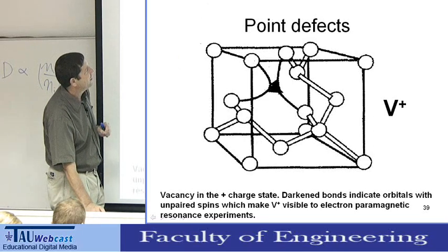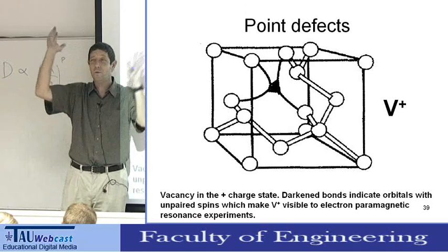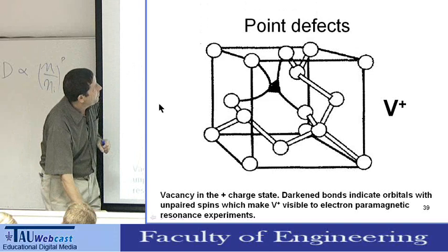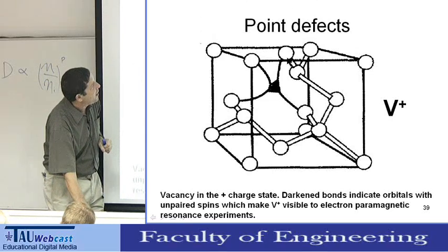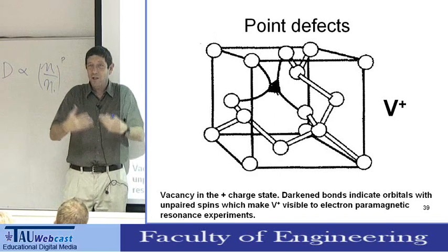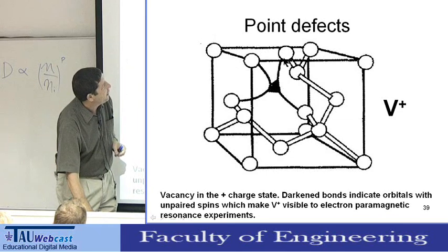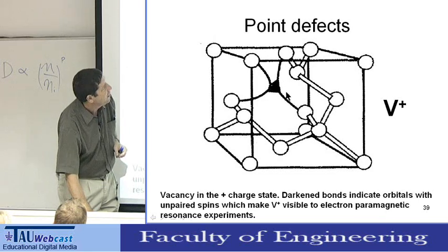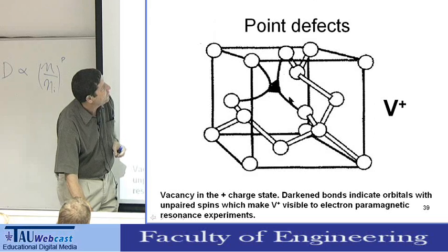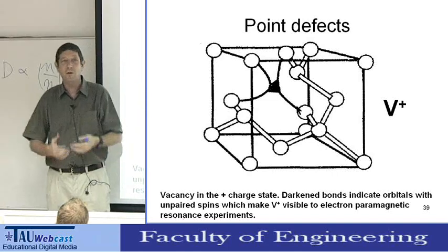This is a vacancy. Here we miss one electron, one atom. The atom went somewhere. Now remember that you have other silicon atoms here, and here we have some missing bonds, because initially there was an atom there, but the atom went away, but still you have 4 electrons coming from the sides. Initially there was an atom here, so depends what happens. We have 1, 2, 3, 4 bonds, and these bonds can be either full with electrons, empty, or partially